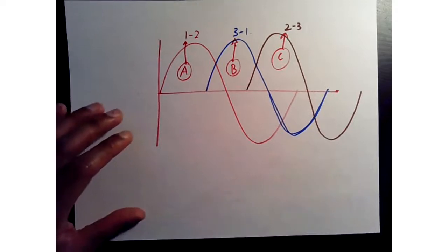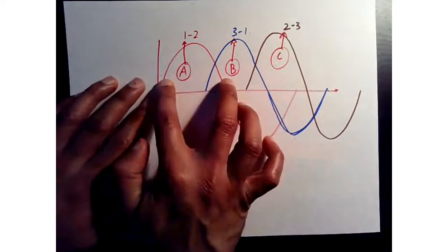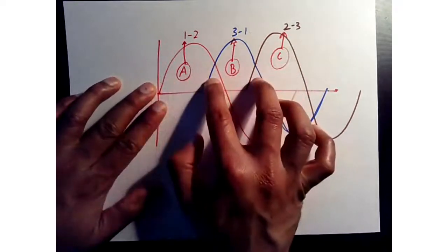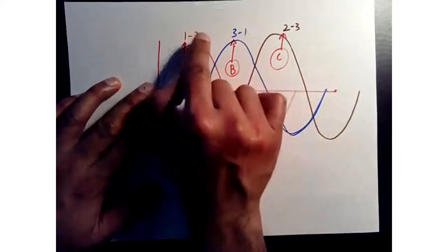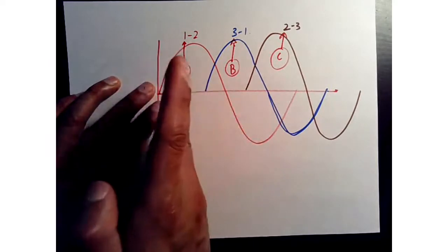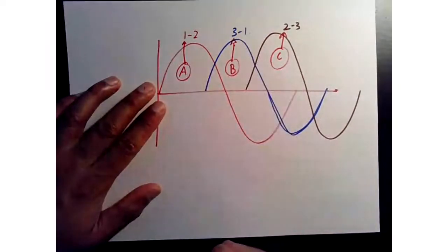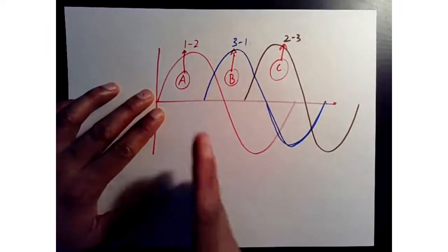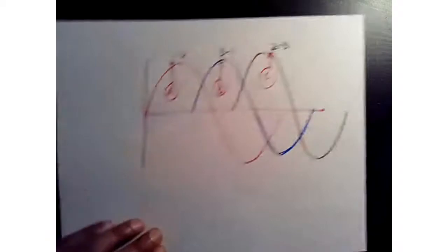And sometimes, in the worst case, you can see something even a little bit different. You could see 3 to 1 here, 1 to 2 here, and then 2 to 3 here. So first of all, start with selecting one of them, name that first one A, and then look at the relative phasing between them to name the rest of the phases. Okay, that way you can name the ABC sequence for that chosen direction of rotation. Okay. So we have the direction of rotation done.